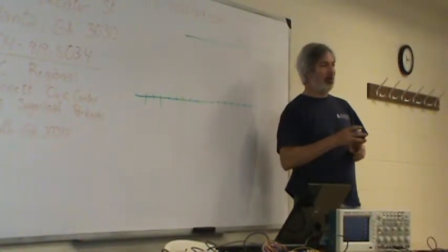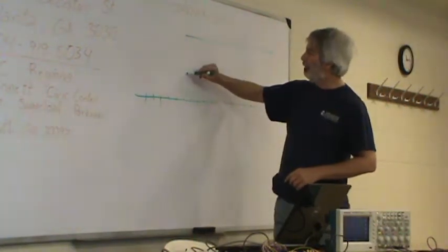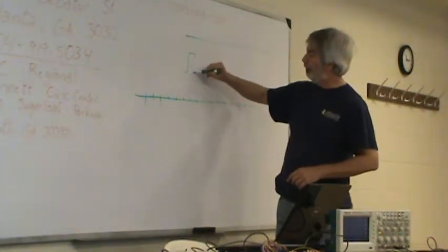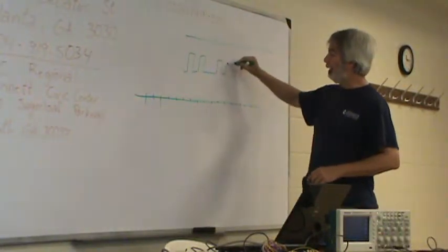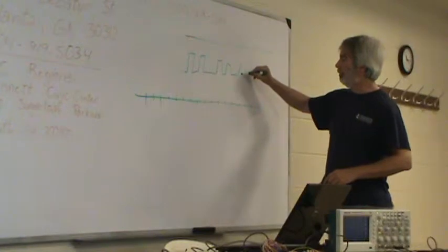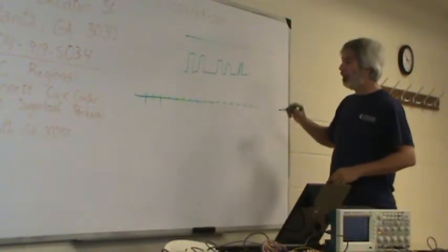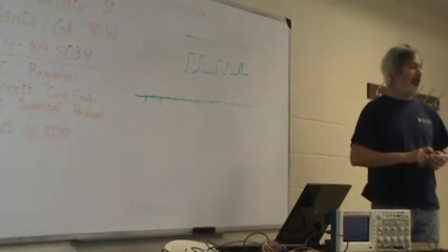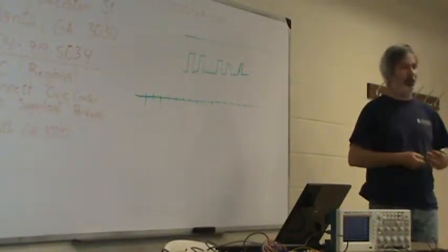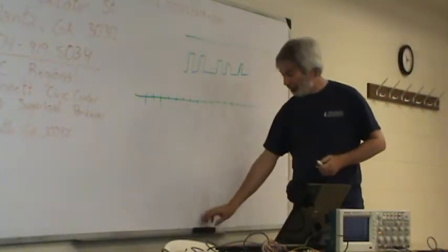Once you do have it set up properly, essentially what you'll end up with is basically a square wave pattern. It will usually be a very irregular pattern. Oops, well, that one's square, not round. And it becomes very obvious very quick that yes, I am properly on the transmit pin.